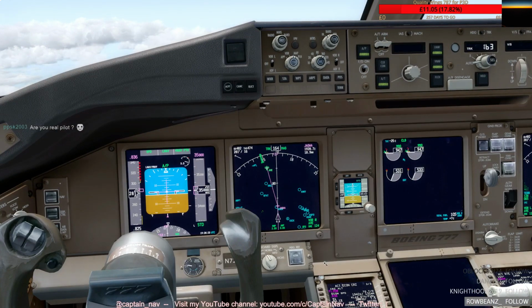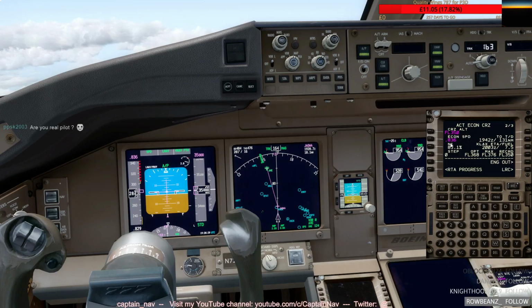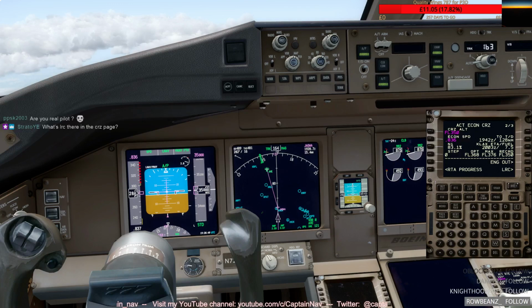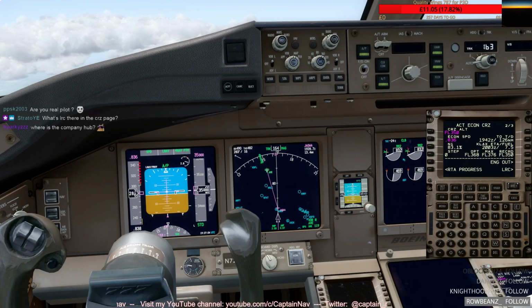And the difference here, I've shown between 120, which is simulated here as .836, which is possibly, I mean, the numbers change depending on the temperature and on the winds, on the wind component above all. If it's a headwind, the Mach number for a given cost index is going to be greater than for a tailwind, because with a tailwind the system is going to benefit from the tailwind and not look for so much forward speed in the air, if that makes sense.